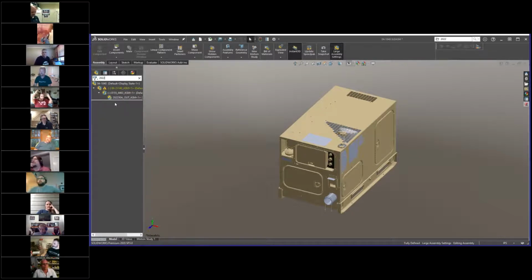You know, Cam, after you showed us that in our planning session, I went to give it a try, and for the life of me, I couldn't find the filter. And then I think it needs to be resolved. Yep. You're probably right. It's an option in the feature manager section of the system options to enable the filter. And you can only toggle that option when you do not have any documents open. Well, it was working for me. Yeah, so you probably already had it turned on. But for me, I didn't.